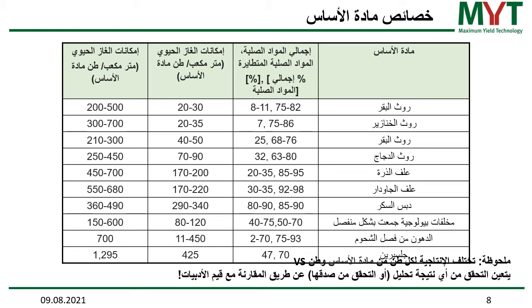And as you can see, there's a lot of variance in the different substrates, but in general, substrates such as energy crops, for instance corn silage or rice silage, have a very high specific biogas potential, whereas cow manure, pig manure, and chicken manure have a lower specific gas potential, because the original organic material has already gone once through a digestion process.